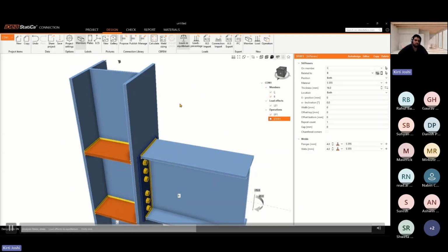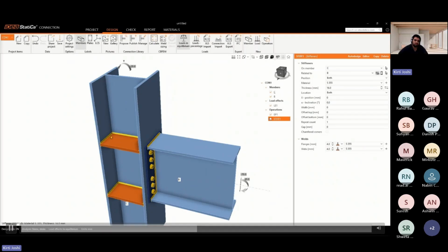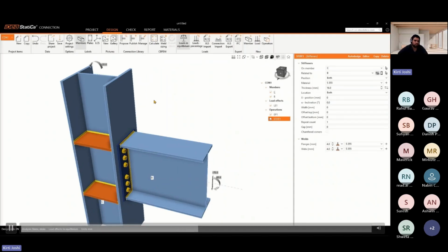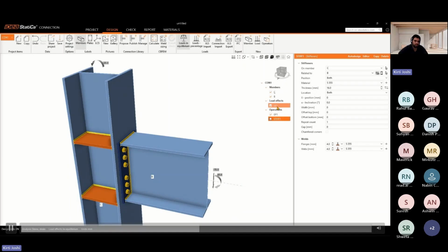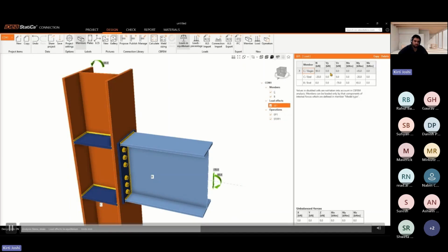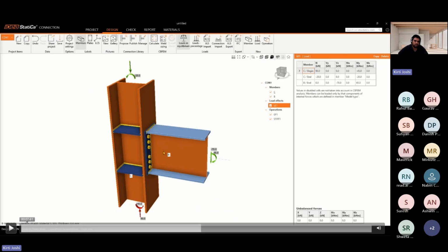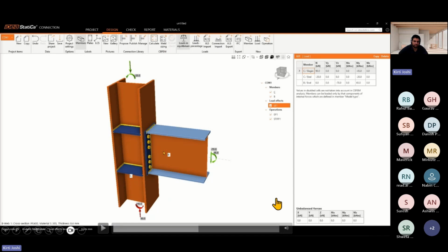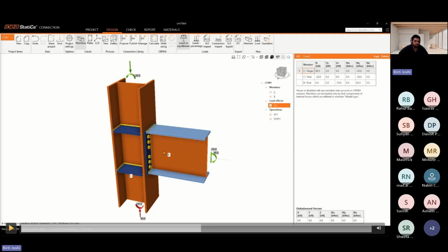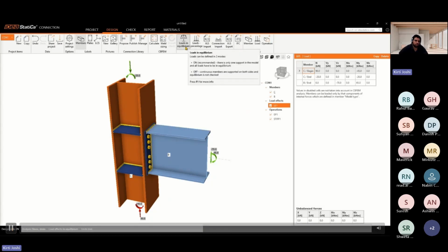So this is related to the operations stiffener and the inlet. And right now you can see my column is there, the beam is there with the stiffener and the inlet connection. So we'll just check out the load. Right now in the load feature, you will see at the top, there are two options, the loads in equilibrium. Once you click this option, it will calculate the unbalanced force, that is the sum of the verticals, the sum of the equilibrium. The loads in equilibrium must be 0. So I'm using this loads in equilibrium feature.